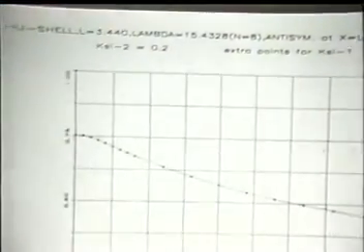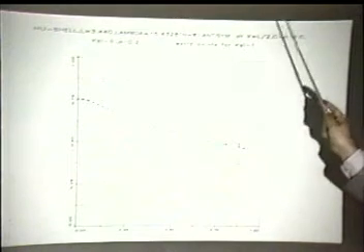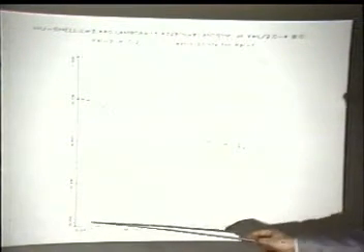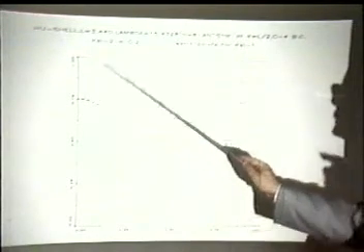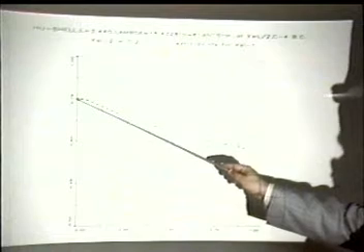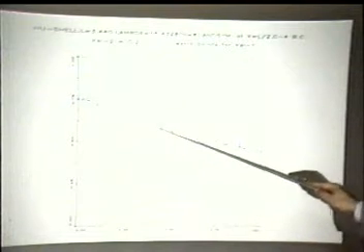Now, the other thing you might wonder is, okay, how can I represent this information? What we have tried here is the following. We said, essentially we have a three-dimensional space. Here you have rho, that's lambda divided by the lowest value to normalize perfect shell behavior to 1. Here you have Xi1, and here you have Xi2. We set Xi2 equal to 0.2. So even when Xi1 is 0, you still have Xi2 equal to 0.2. So it will bifurcate here. And then as you increase also Xi1, you get the limit point and you get this type of behavior.